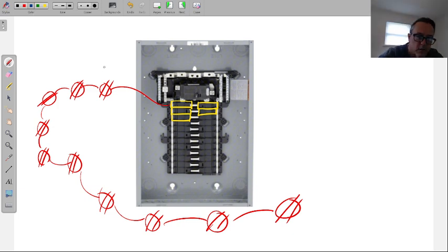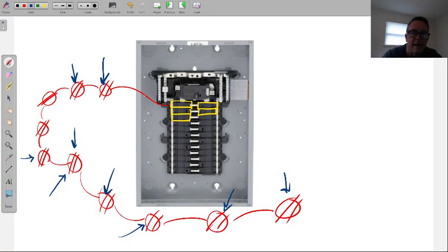So here's what starts to happen. People plug in, bring in something to this room. Somebody just bought an air conditioner, wants to put it there. Mini fridge goes into this bedroom. Plug in, and what you're starting to do is add amperage to this circuit. Well, you are limited to what we said, 15 amp breakers. So at some point, this breaker is going to pop.